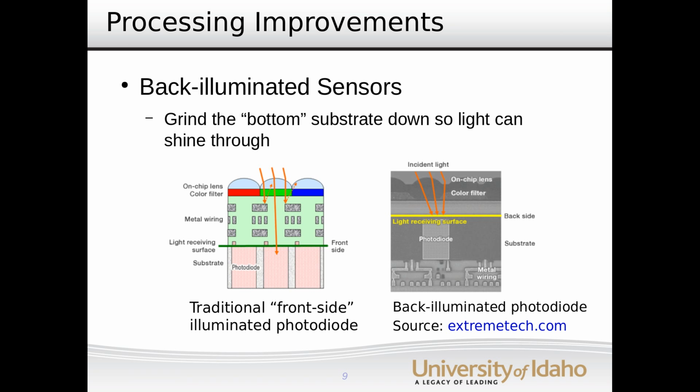And then you can add your anti-reflective coating on top of that. So you can get more direct light to the photosensitive area of your photodiode with the back illumination, which is very important for UV light. You're not going to have as much reflection and get a lot more direct light there. But you've got additional processing steps, and then you've also got the passivation layer and electron traps that you're going to have to pay attention to.